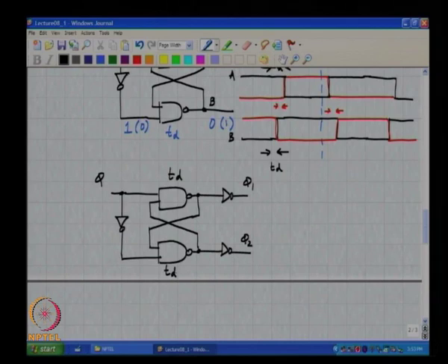And these are in many cases deliberately made, especially when you are dealing with very low frequency signals. You want to be absolutely sure that the two do not overlap when the clock rates are not very high. In very fast technologies it is often very difficult to get sufficient delay in the gates. So, you put a chain of inverters in cascade, where you deliberately want to make the gate delay slow, so that you get an appreciable non-overlap time.